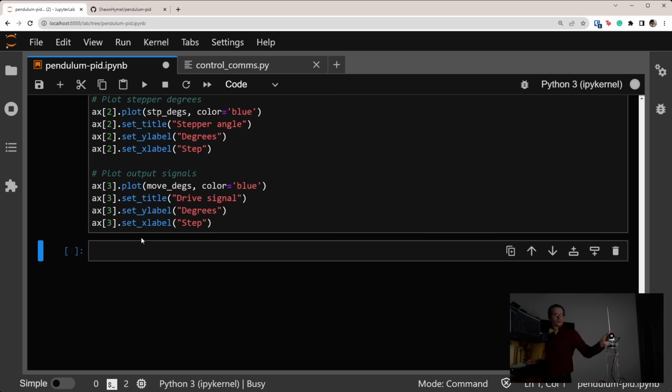Okay, not bad. There's some oscillations, and in fact, I want to run this again. Be prepared to run some of these cells multiple times. Okay, still some oscillations. It's oscillating around that 180 point, so it means it's a little too high still. Let's bring it down just a notch. We're going to take it to 0.3. Let's see what happens. Oh, that's really good.